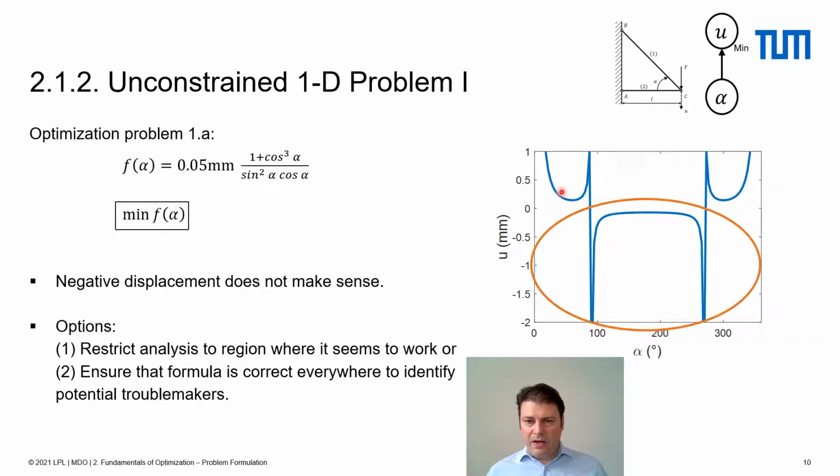And when you think about it, at an angle of 0 degrees, displacements would be very large, because there is almost no resistance against deformation if you make these rods very close to each other. Well, upon increasing alpha, the stiffness of the structure, of course, would become larger, therefore the displacement would become smaller.